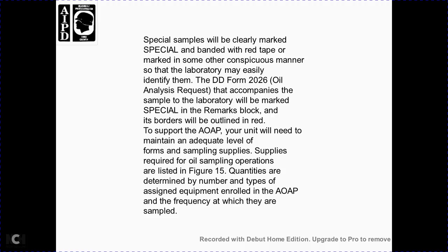Special samples will clearly be marked special with a band of red tape, marked on the other constituent bands, so that the laboratory can easily identify them. The DD Form 2026, the oil analysis request, that accompanies the sample to the laboratory will be marked with a special remarks block with borders outlined in red. The Army Oil Analysis Program.